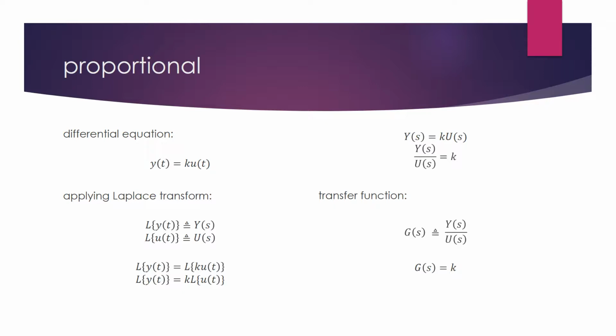One of the most important applications of the proportional controller, fixed bias or offset, is the zero load process. It means the dynamic characteristic of the process doesn't get any disturbance even as flow doesn't get through the controller for a small duration. In a proportional system, the output is just proportional to the input, with k being just a constant. After applying the Laplace transform on both sides, we change y(t) to Y(s) and u(t) to U(s) to finally get the transfer function equals k.